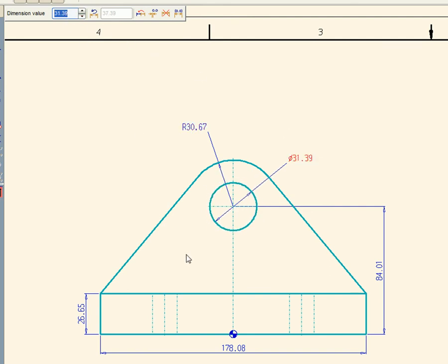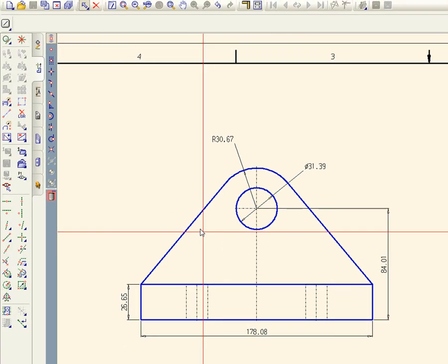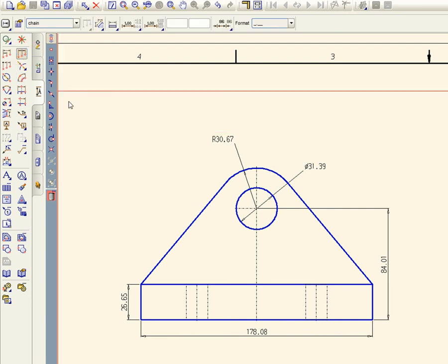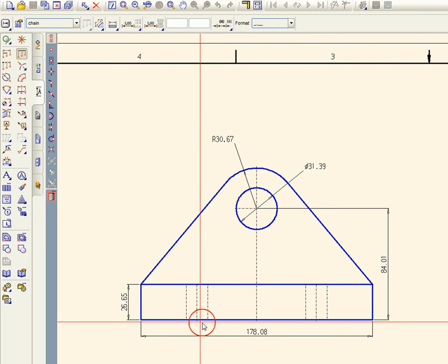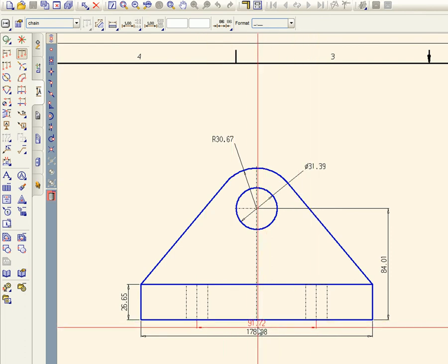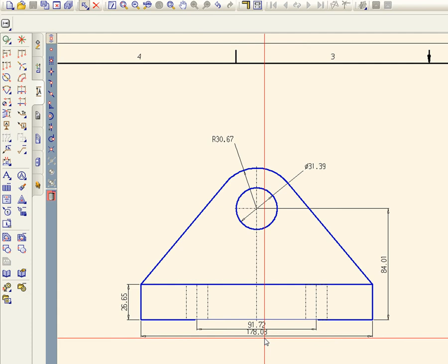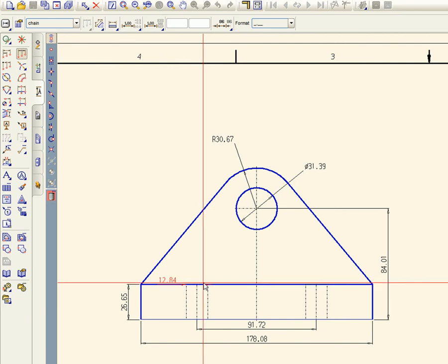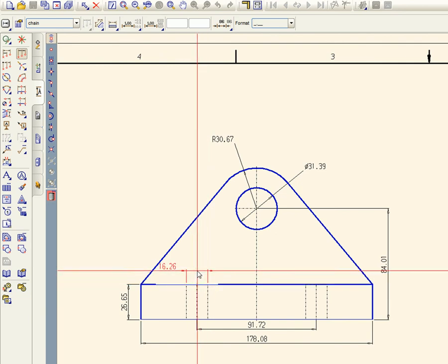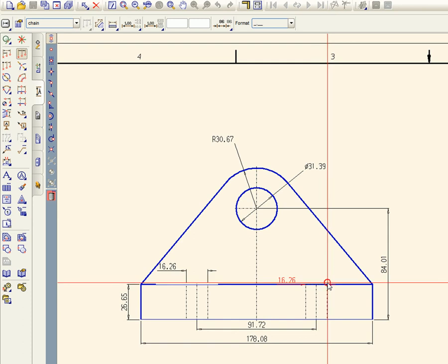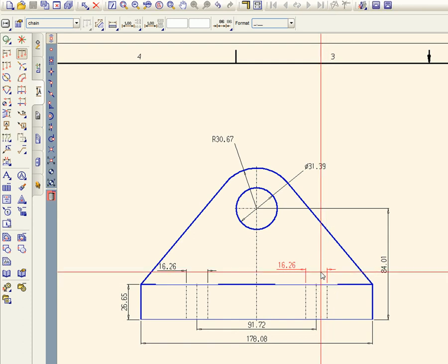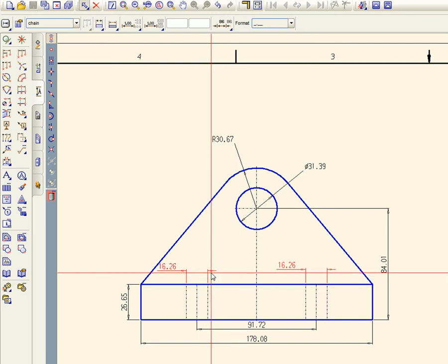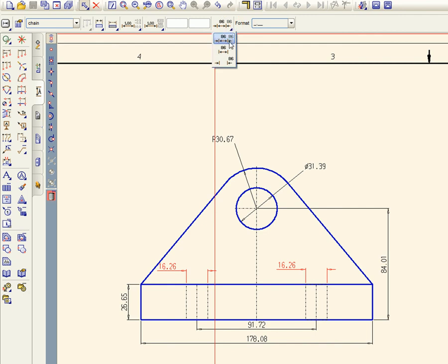I'm still missing a few of the dimensions I need in order to dynamically edit the entire drawing, so I'll just go back to the Text and Dimension tool tray and I'll dimension a few additional areas. So from these center lines here, and then also I can dimension the boreholes. Basically everything that I'd like to be able to edit later on, I want to dimension right now. You can see that the context-sensitive dashboard above lets me change the properties of my dimension text as well.